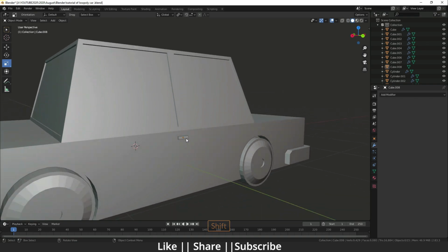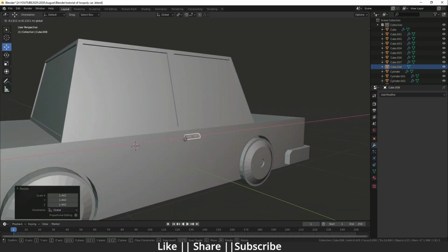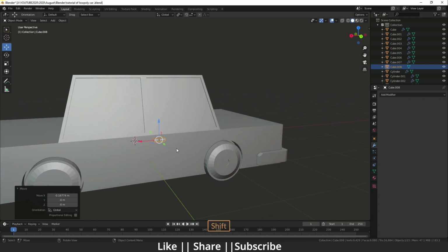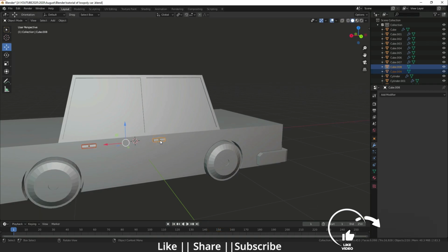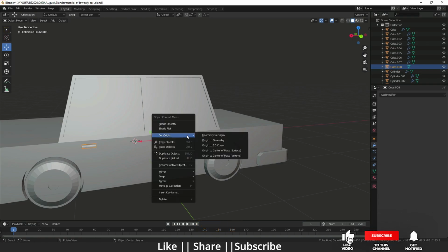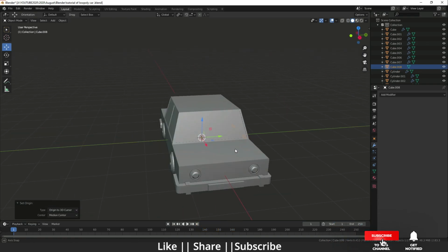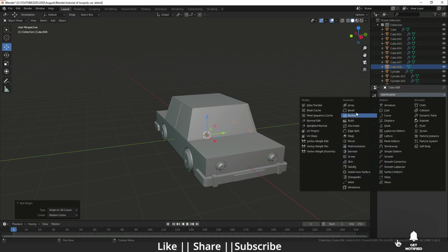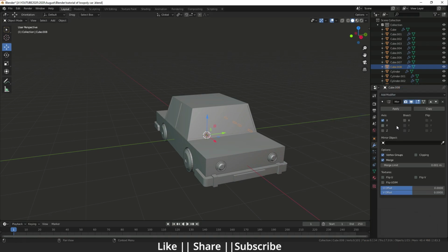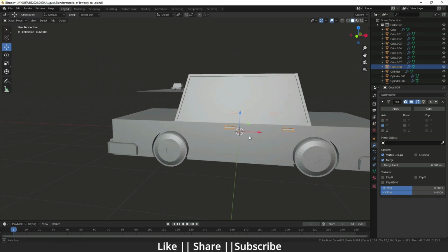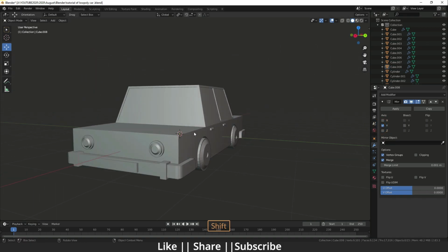Okay, and if you want to increase the size a little bit, now you can increase it, and just keep it here, and just press Shift R, Shift D, and keep one here, and just select both and press Control J and set the origin point to the 3D cursor and add the mirror modifier. And select the direction, so we have the same thing here also.